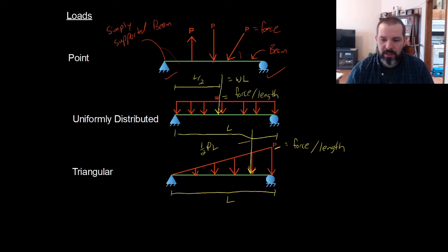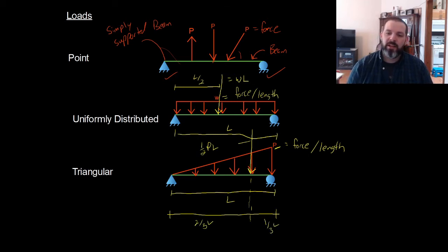It is located, I'll write it down at the bottom, 2/3 L from the skinny end, or 1/3 L from the fat end. In order for us to work with any of these distributed forces, be it uniformly distributed or triangular, we need to find the resultant force.